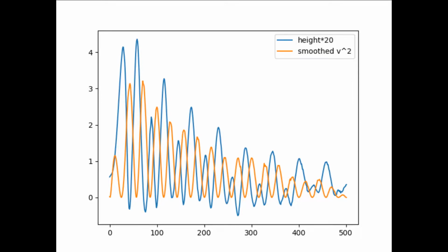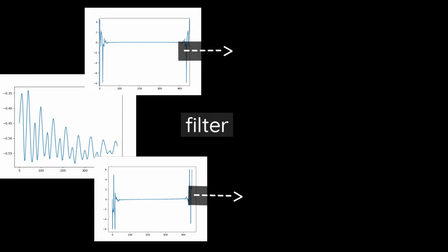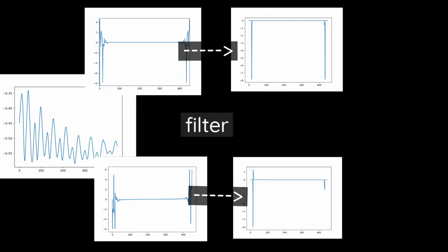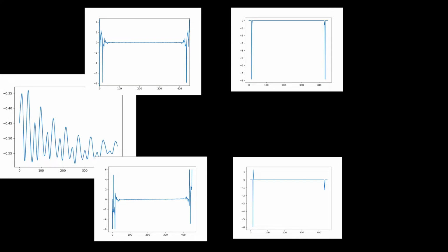Although anything past this point, we are starting to get into that range where you're doing so much number crunching that you have to be careful you're not just removing things of importance. So anyways, using the Fourier transform, you can get some sort of frequency spectrum. And then you can remove portions of the frequency spectrum, either lower bound frequencies or higher bound frequencies. And that way you can get the frequency that you expect.